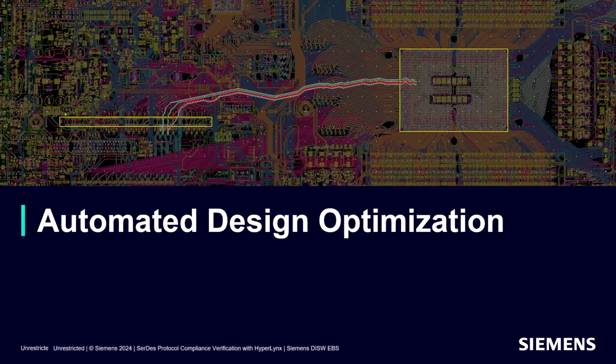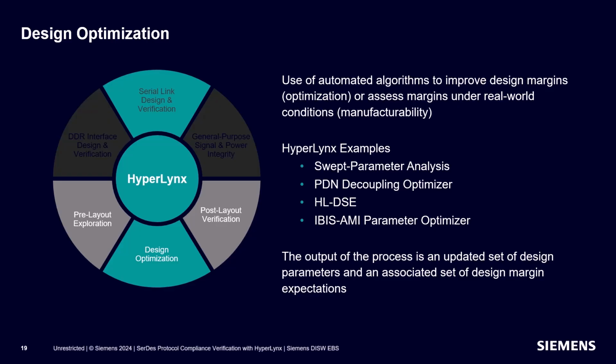Now let's talk about automating and optimizing your design. During pre-layout serial link simulation, 3D Explorer and S-parameter analysis is commonly used when exploring schematic topologies. We also use independent tools such as Design Space Explorer to perform more intensive optimization of specific structures like breakout vias. We'll explore that next.